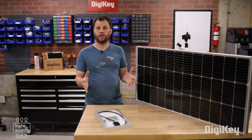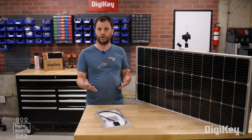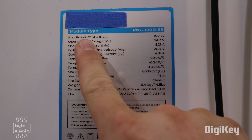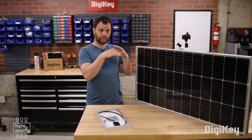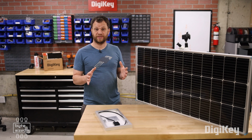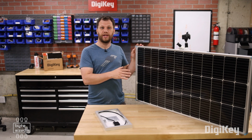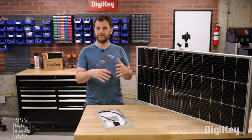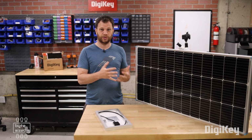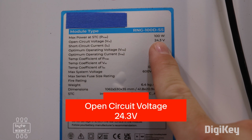The best place to start when trying to understand maximum power point tracking are the specs printed on the back of your solar panel. In this case, I'm going to be using this 100-watt solar panel, and the specs that I list here are going to be different than the panel that you might be using. The first piece of information I want to know about this solar panel is its open circuit voltage. This is the voltage that is measured across the terminals when no load is applied to the solar panel. In my case, that's 24.3 volts.